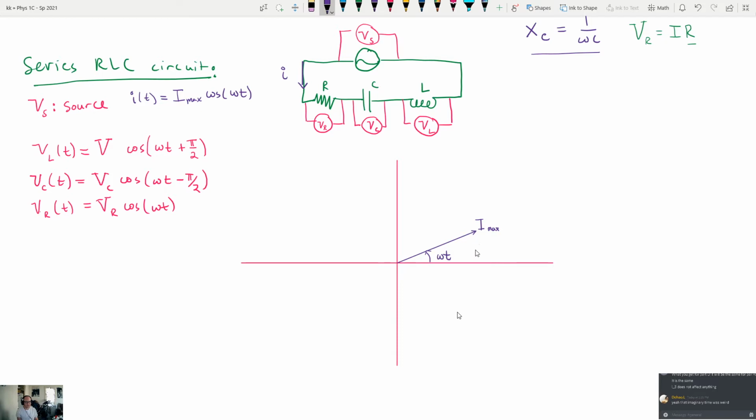If omega is 2 pi radians per second, how long is it going to take for my phasor to go from its initial position here at t equal to 0 all the way around 1 time? Supposing that omega is 2 pi radians per second. How long will it take? Just 1 second. So what you should imagine in your mind is that you have this little arrow that rotates around once every second. Every second it goes around 1 time, basically like this.